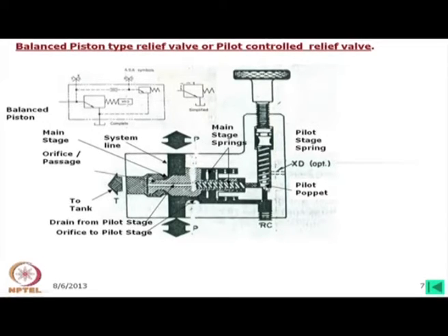Now, when this opens, flow is coming through this. What will happen? There will be a pressure drop. Due to this pressure drop, there will be a reduction in the force on this side. Remember, this side force is high, this side force is less. So this one will move inside.